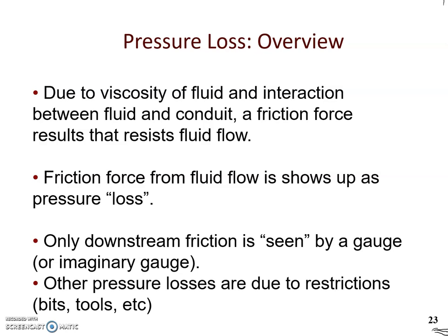Usually these pressure drops happen due to the friction in the conduit, drill pipe, drill collar. But also it happens inside the drill bit, inside the tools that we have, through the chokes or any other restrictions that we have inside the wellbore.